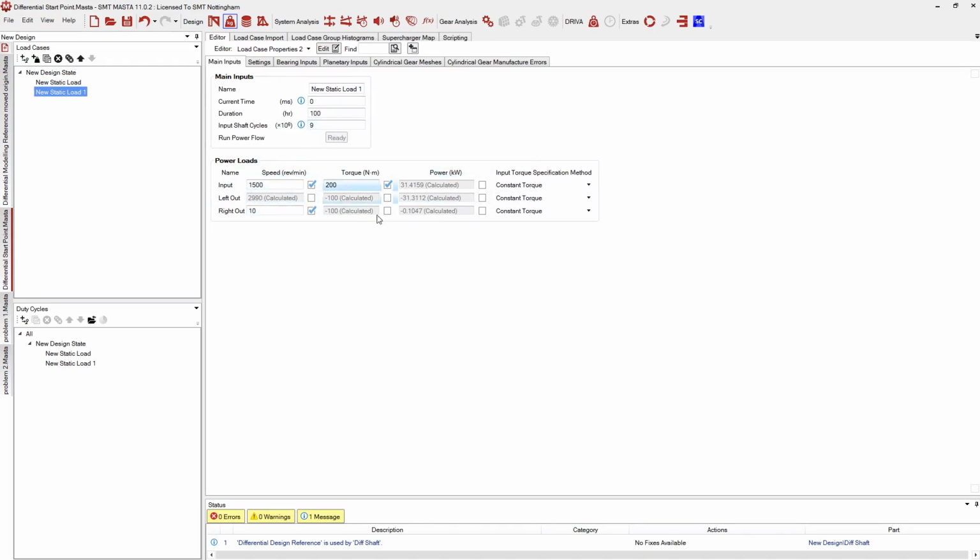There we go. So all I did was a slight change to the actual shaft dimensions there. It just confirms to the unit that it is actually connected to the component it thinks it's connected to. So if you do see that error on one of your gear sets, just have a play around with the shaft dimensions and just make sure everything looks like it's connecting in your 2D view. There's no gaps, for example.